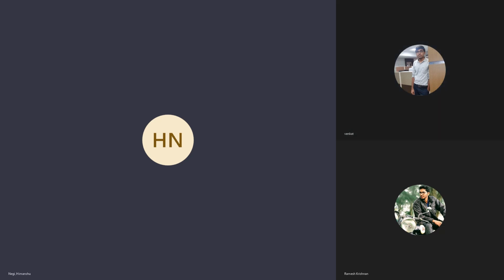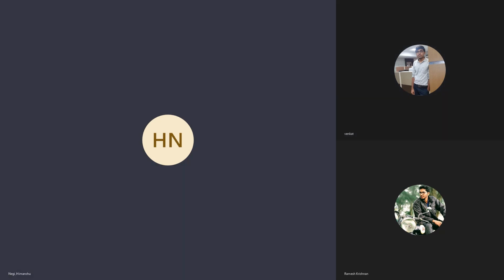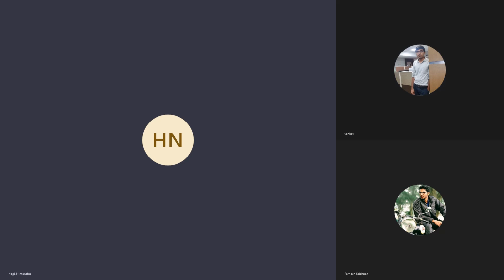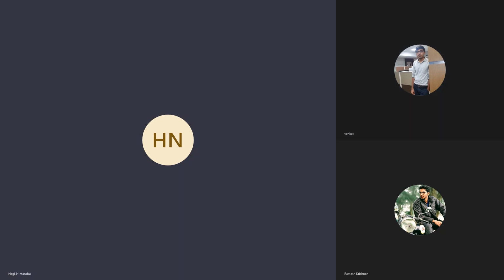Now, when I talk about a sealing end tower, this is how the tower looks. Basically, this tower has some kind of arrangement on the top. It depends on whether it's a single circuit or double circuit. The phases are terminated here with insulators. There are surge arrestors, and then they've got these metallic sleeves. The cable comes down through these, and after that the whole route becomes underground, which I am showing you here, right?